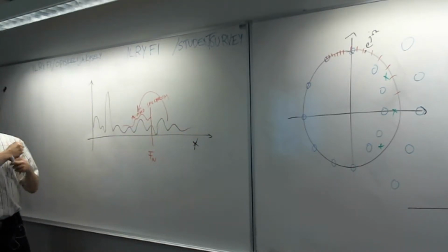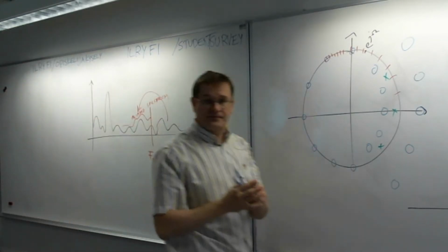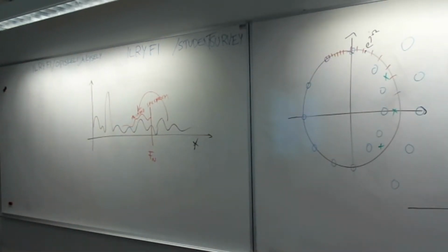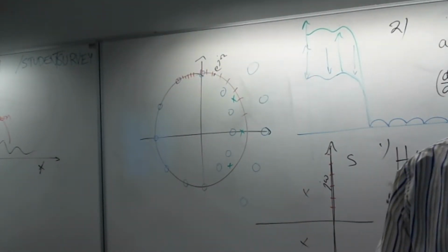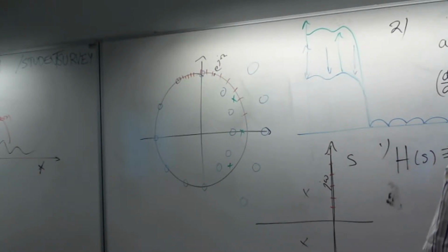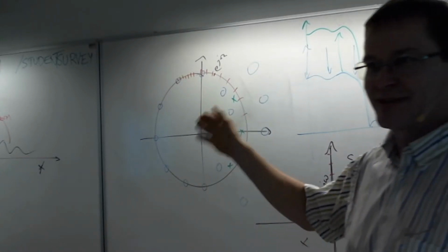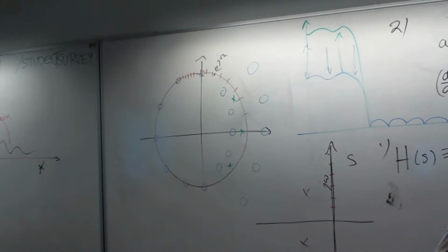Okay, and then it works since there's nothing to alias. All right. Third method. Yes, it's possible to just create that with a really high sampling frequency first, and then you have discretized it and you filter it again. Yes, decimate it. Do some digital filtering and stuff like that, and drop the sampling rate.